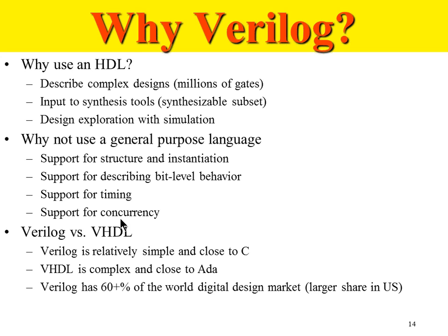I need timing control inside the chip to control various aspects of my logic. That timing control I can get using Verilog, specifically, but I cannot get it using C language or any other programming language. So Verilog gives me the functionality to control timing using the clock frequency on the board. If you look at any board, an FPGA board or any other general PCB, there will always be a crystal oscillator which is generating the clock for that board.